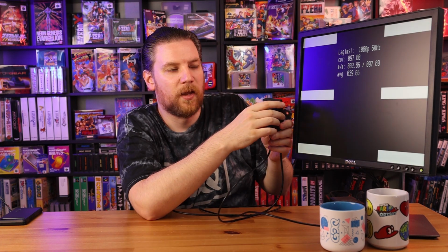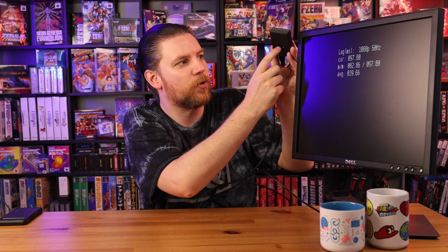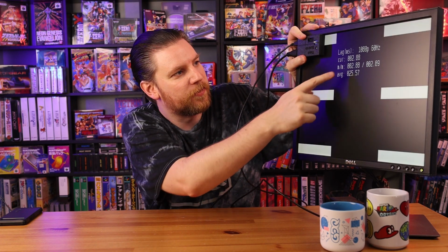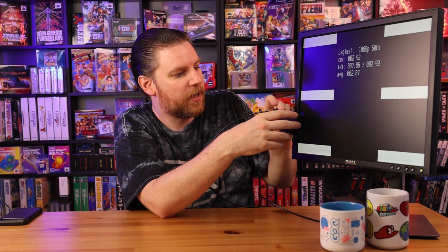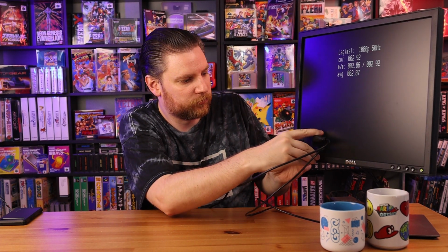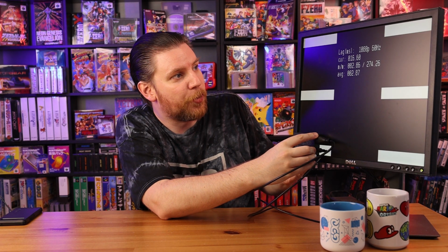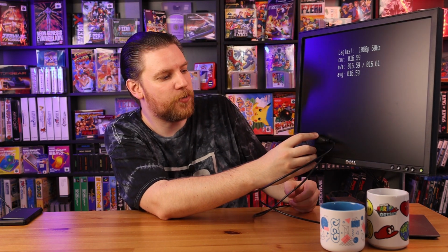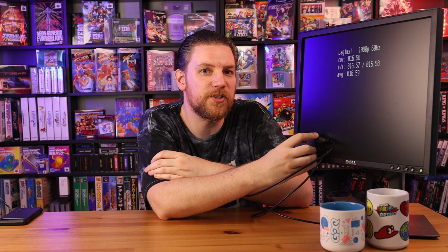And then for the top bar up here, to see where the signal starts, I have to hold the Time Sleuth upside down because of where the photo sensor is, to get it all the way up in the corner to barely be able to register that signal. And you can see we are a little under 3 milliseconds at 2.86 milliseconds. And if we go all the way to the bottom of the screen, we are at about 16.6 milliseconds. This number here is very important to note. If you're running at 60 Hertz, 1000 divided by 60 is 16.6, so 16.6 milliseconds.